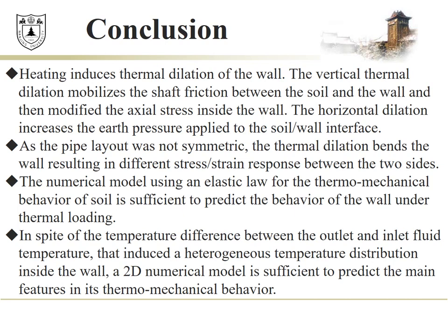Third, the numerical model using an elastic law for the mechanical behavior of soil is sufficient to predict the behavior of the wall under small loading. Fourth, in spite of the temperature difference between the outlet and the inlet fluid temperature that induced a heterogeneous temperature distribution inside the wall, a 2D numerical model is sufficient to predict the main feature in its thermo-mechanical behavior.